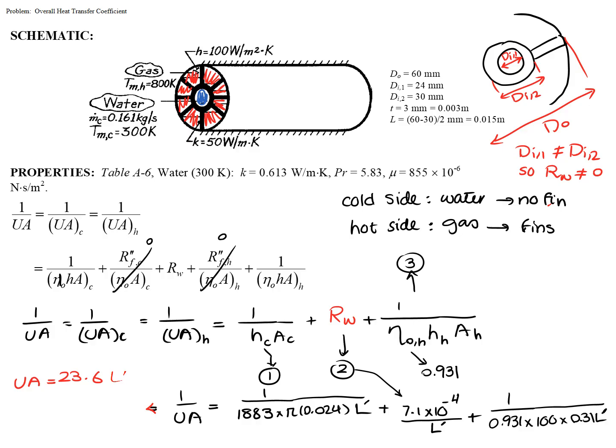The reason we haven't done that is we have no idea how long this tube is, and without that information, all of our calculations are going to have some degree of error anyway. So we're just sticking with the 300. I could assume 400 and someone could tell me, well, this is a very short tube, you're not even going to get close to 310. And then I could pick 310, and someone would say, well, if this is long enough, you may actually arrive at 500 at the exit of the heat exchanger. Because we really have no idea how the average is going to look, we're just picking 300 at this point, and we're getting the properties. Hopefully this is close enough to the actual values.